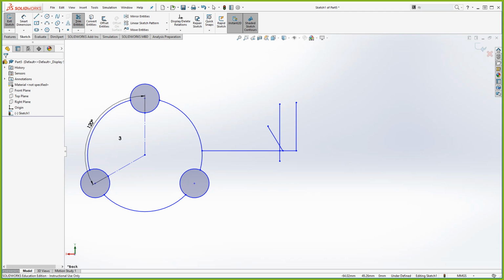So I'm going to be giving you guys some more examples. Just make sure that from today's first part of this class, I guess, you know how to make a plane to a sketch. You know how to link your sketches to the origin, how to sketch basic shapes like line, rectangle, circle, ellipse, and arcs. You know how to dim and define your sketches, dimension and define. You know what the difference between under defined, fully defined, and over defined are.